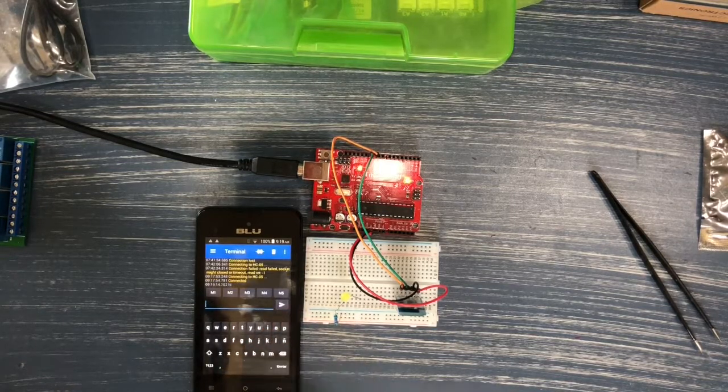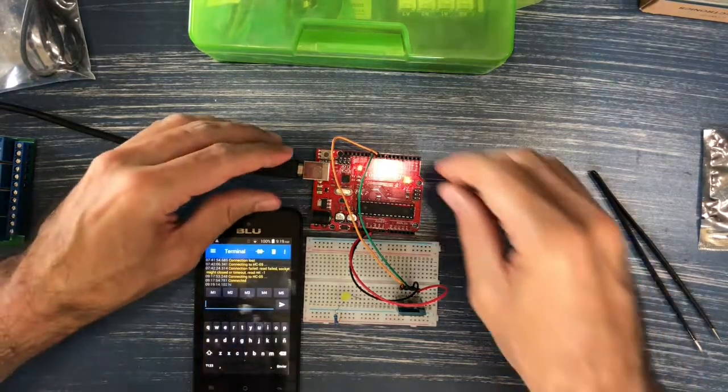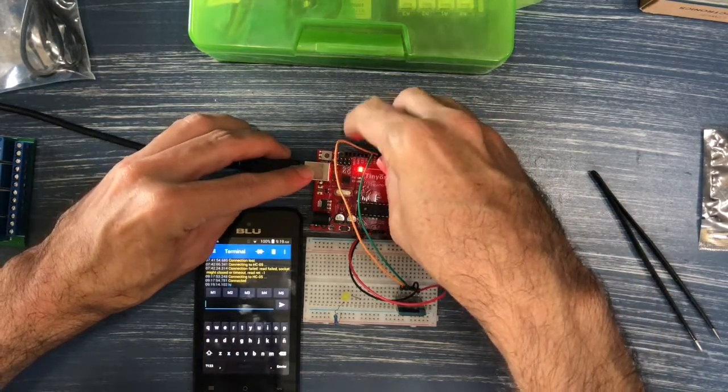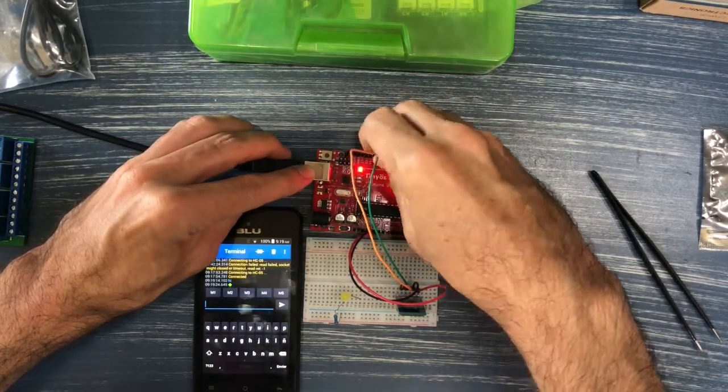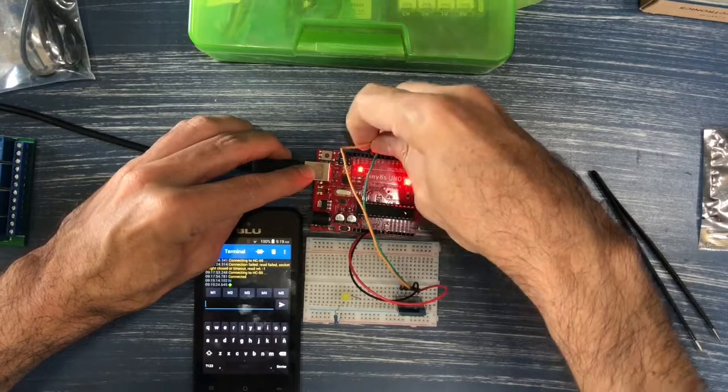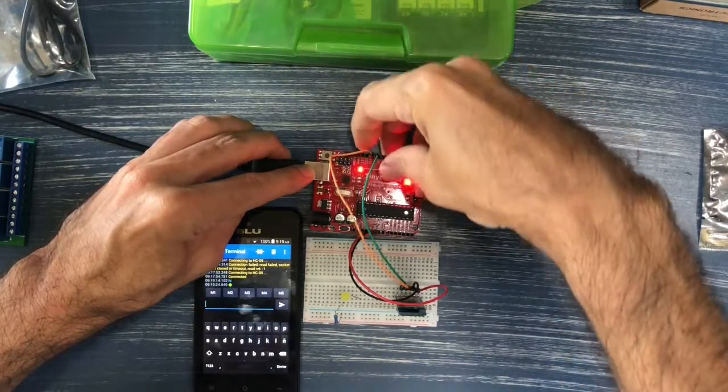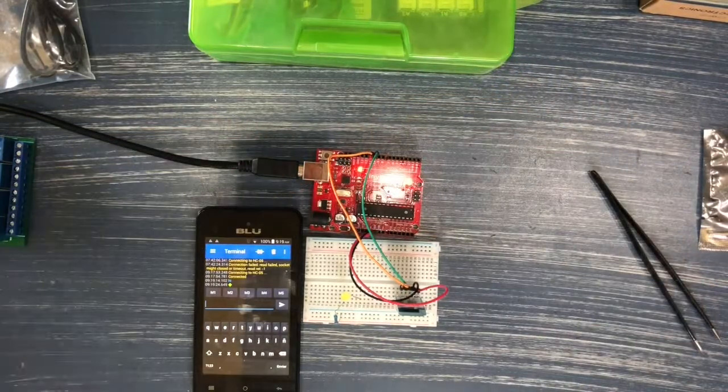Let's see if we can send and receive. So I sent the word hi to the Arduino. The cables seem to be the other way around. Sorry about that. That's why I put up that slide, where it's important to always keep in mind that the RX and the TX switch around from module to microcontroller.